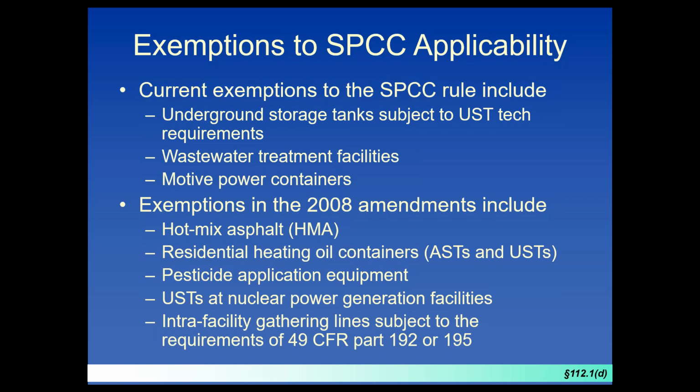If you have a yard where you're doing work, like a construction yard or maintenance yard, we don't regulate pesticide application equipment. You might ask why. In the pesticide formulations, there's something called adjuvant oil, and the adjuvant oil itself is an oil, and so when you mix it with the agent, the pesticide or herbicide, that mixing container and any application is exempt, even though there's oil in it. Now, the adjuvant oil, if it's stored on its own and the facility is otherwise regulated, that is regulated. Typically it won't be, because adjuvant oils are typically in containers less than 55 gallons. There have been some IBCs and other plastic containers that may be a little bit larger, but that's important. So we only regulate the adjuvant oil when it's on its own.